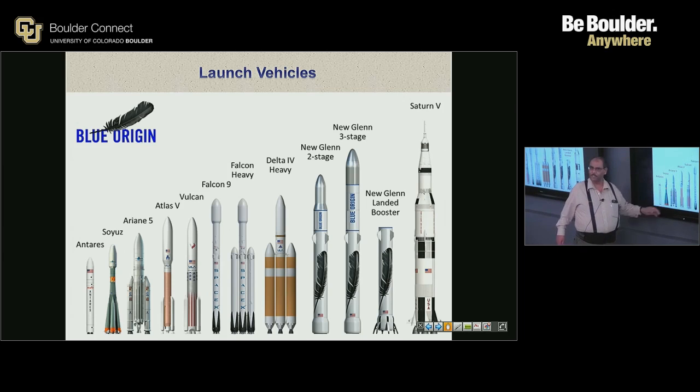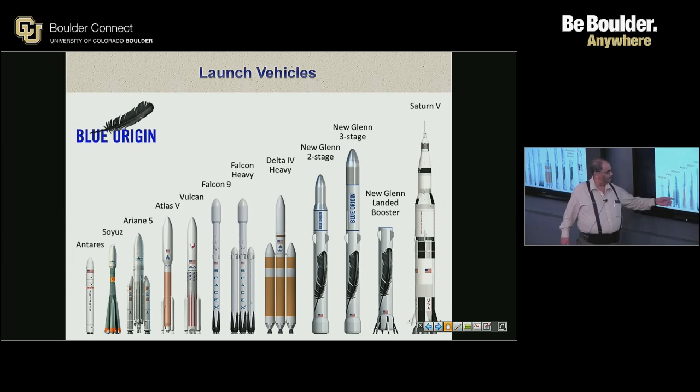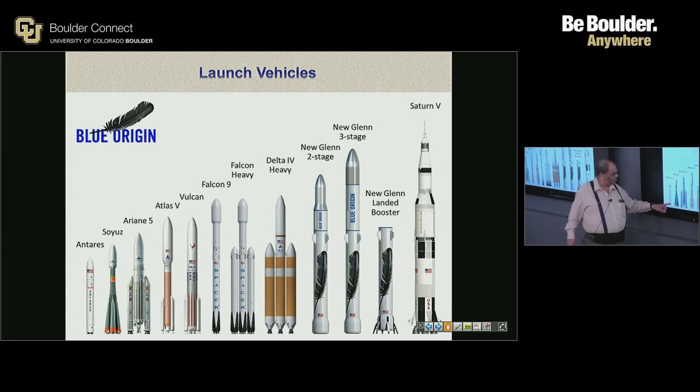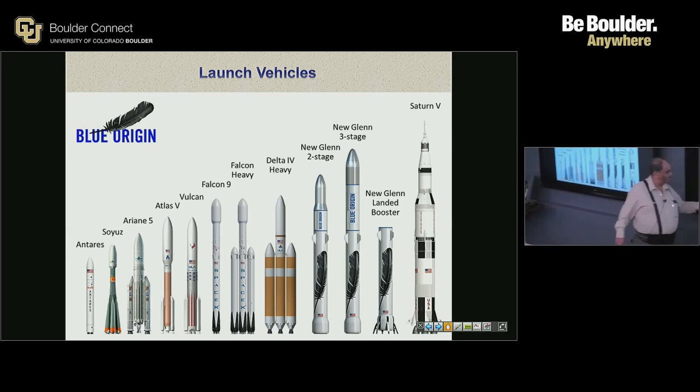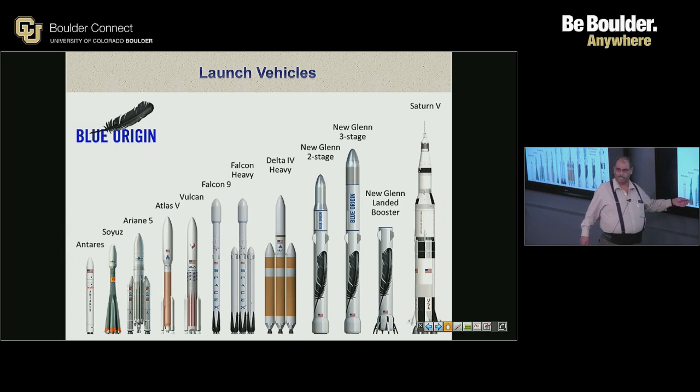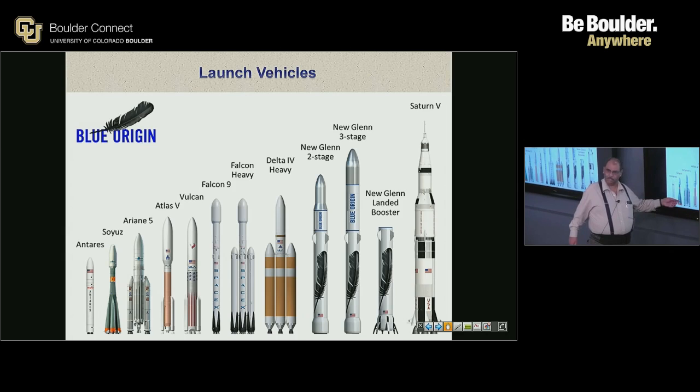Ariane 5, the European one, heavy launch vehicle, parallel staged. This is also parallel staged. You see these 4 cone-shaped things. Those are the boosters that are discarded. Okay, so this is actually a modified version of the first ICBM they built to launch hydrogen bombs, capable of launching hydrogen bombs towards us. But anyway, parallel stage, 2 solid rocket boosters, main engine cryogenic. The upper stage cryogenic. They used to use a hypergolic one, but then they replaced it with the cryogenic one.